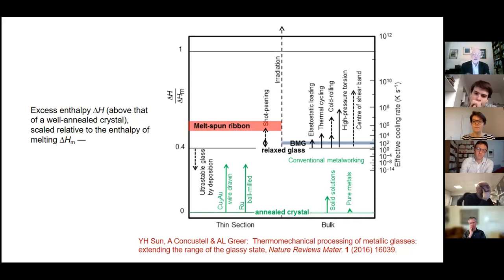My interest in this talk is principally about if you do have a glass, what can you then do to it to change its energy? And in particular, I'm going to be interested in what you can do to increase its energy. And there's a reason for that. It's well known, especially for the glasses of importance for their magnetic properties, that if you anneal them, which is quite a good thing to do to improve their soft magnetic properties, they do become horribly brittle and difficult to work with. Of course, you don't want them to show that embrittlement. You'd like them to show something in exactly the opposite direction, becoming more difficult to crack. And that would mean increasing the energy of the system, so doing something that's opposite to annealing.